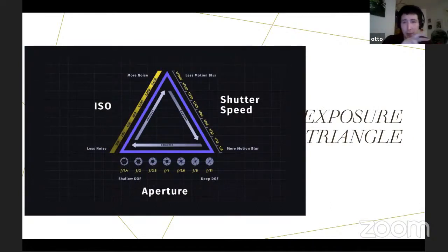These three aspects of photography play into what's called the exposure triangle, where they're playing off one another. In photogrammetry, the exposure triangle is somewhat easy to understand because two of the aspects are fixed. Your ISO is always at 100 and your aperture is generally about f5.6 or f8. Those are quite slow settings, so it's good practice to always bring a tripod along with you, because your shutter speed, which is your one variable, is always going to be quite slow, depending on the light.